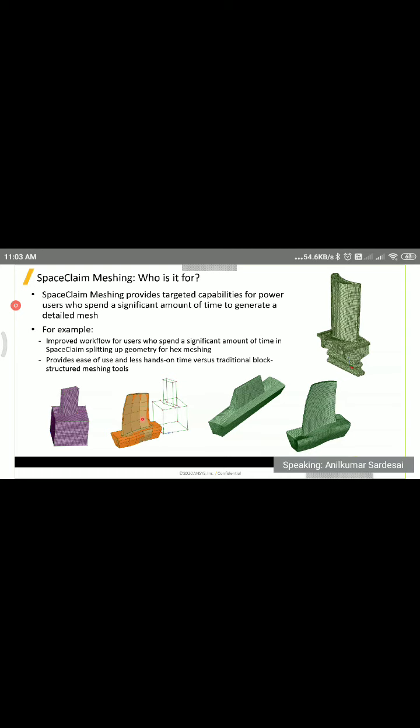So the next time I'll just import my new model and this old mesh, and automatically it will be associated, because everything is taken care of as a name or as the number of edges which are going to interact. The number of edges doesn't mean that if here I have one, then here I should have one. It can be 10 edges, because I'm going to match this node and this node. It doesn't matter how many edges there are in this.